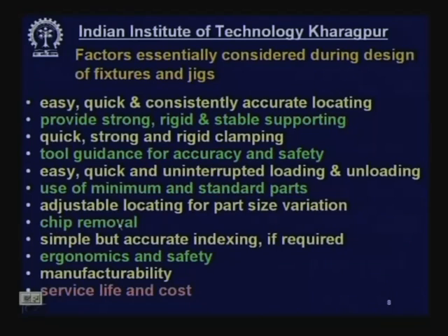Chip removal, yes, it should be taken care of. The chip should not be allowed to jam at certain critical points and hamper the operation of the jig fixture. It should be so designed that chips will be automatically disposed and should be cleaned easily. Simple but accurate indexing if required. Ergonomics, yes, comfort, convenience of the operators and safety of the operator, of the tool, of the machine, everything.